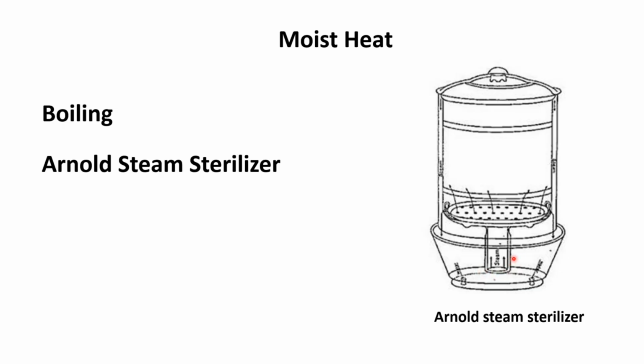The peculiarity of this type of sterilizer is that the steam which escapes from the sterilizing chamber condenses beneath the outer cover and falls back upon the chamber in which the steam is generated. Thus, this sterilizer uses live steam, which has a temperature of 100 degrees, and a single exposure for 90 minutes can satisfactorily sterilize the materials.